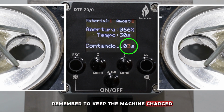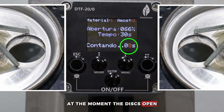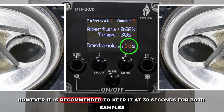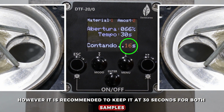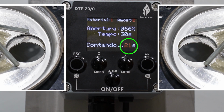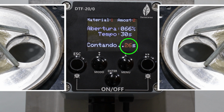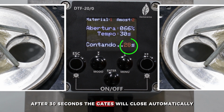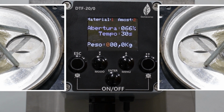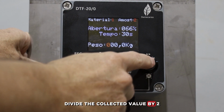Remember to keep the machine charged and the power outlet connected for material output at the moment the discs open. The opening time is a variable parameter. However, it is recommended to keep it at 30 seconds for both samples. After 30 seconds, the gates will close automatically. Weigh the collected material. Divide the collected value by 2.